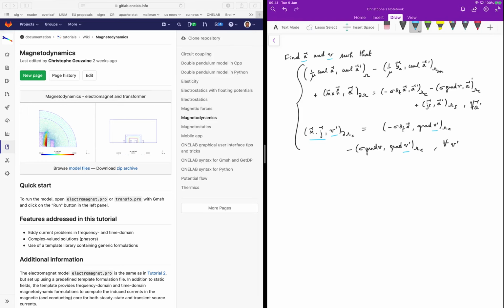So we derived this magnetodynamic formulation in the general setting in 3D, and then we finished the lecture by looking at what happened in a particular case when we had a system invariant along one direction. Conventionally we used the invariance along Z, and then we looked at a 2D simplified formulation in the cross-section, in the XY plane. We saw that you could apply it directly with A, now a vector that would stick out of the plane.